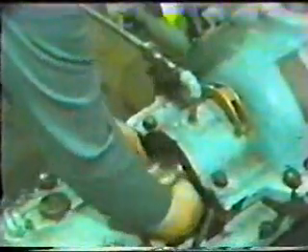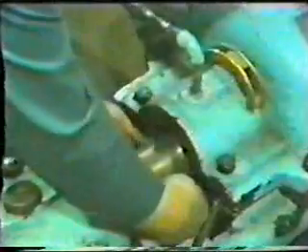One thing you'd have to consider is a packing problem. I'm sure you know that packing is a series of rings placed around the shaft. A lantern ring distributes the sealing liquid to the packing and the shaft. It is important that the lantern ring and the packing rings be properly installed to prevent excess leakage. The rings are compressed by the gland follower to form a seal.